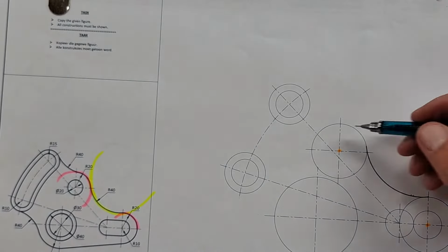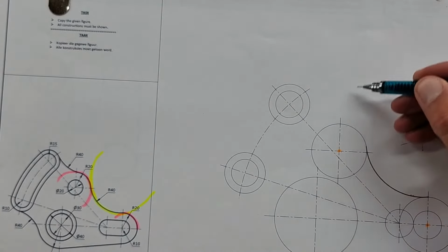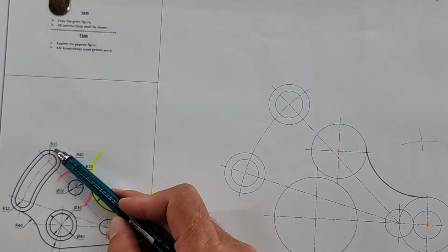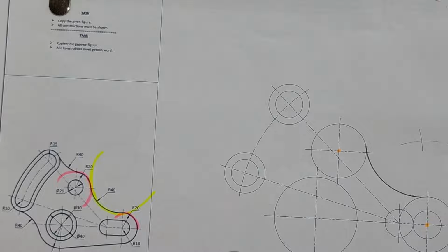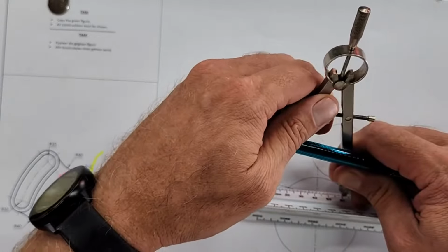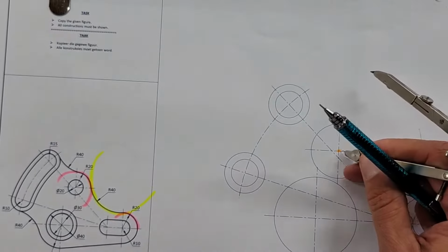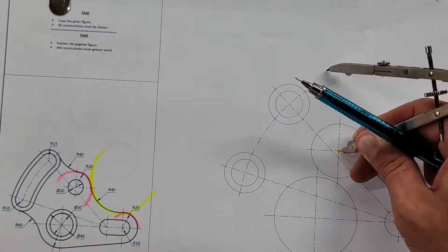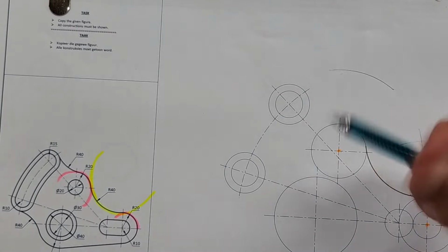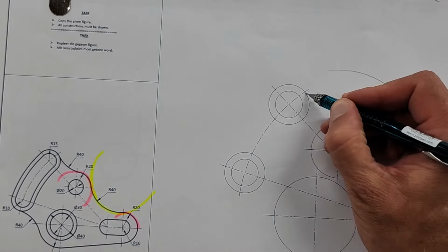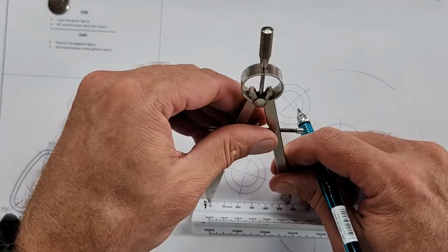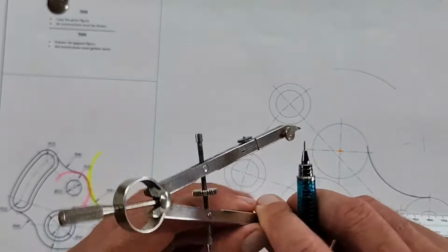Now we have again a radius 20 plus 40, because if you look at this arc, it's again excluding, and the only difference is that on the other side, it's got radius 15. So I'm going to go back to radius 60. I'll do that one first. Okay, there's my radius 60. That's now for this one, the center point for that arc. Okay, and then the circle here on the outside is radius 15 plus that 40 again is 55, clearly. Okay.